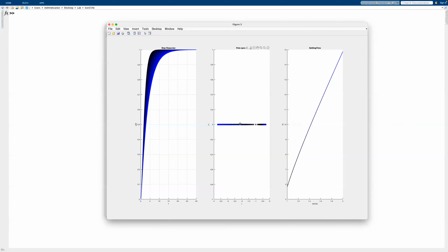like 2 here, 4 divided by 2, if this were a system on its own, would be 2 seconds of settling time. Whereas we can see we have a settling time of 10, 14 seconds here. So within 2 seconds, the fastest one is going to settle down, and we will just have the slow part here. That's the reason why you have this interesting behavior where almost all responses start the same, but then become slower, because this one here becomes active and becomes slower and slower.